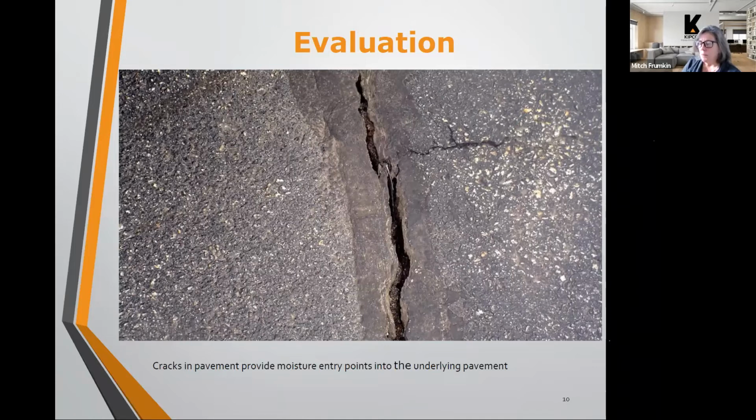those seams open up. There can also be cracks that form in areas of stress in the pavement. There are areas of alligator cracking that can happen where it's almost like these little blocks all over the pavement. But as you can see in this photo, this has been crack sealed several times, and you still have an open crack here because the pavement continues to shrink.